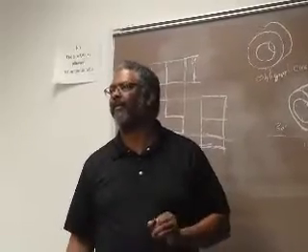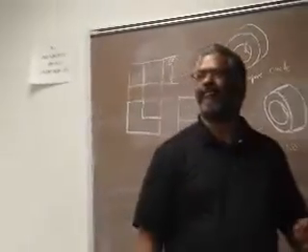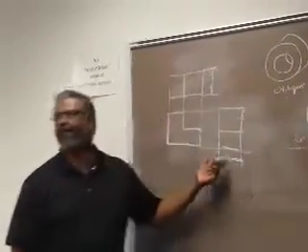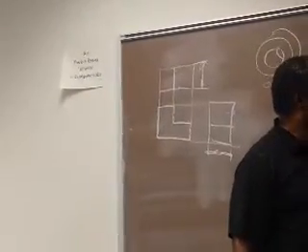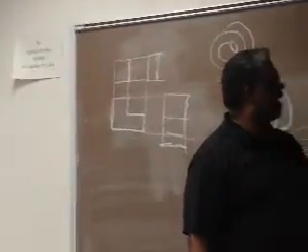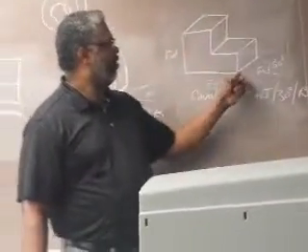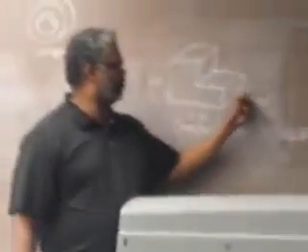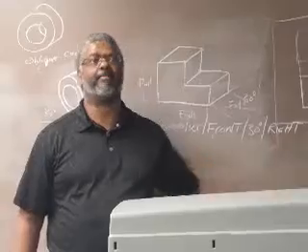So we're just squashing the image, making it exactly the length of the depth in the orthographic view. So this will be a cavalier. We started with the front view, did our 30-degree lines, and drew them to the right.